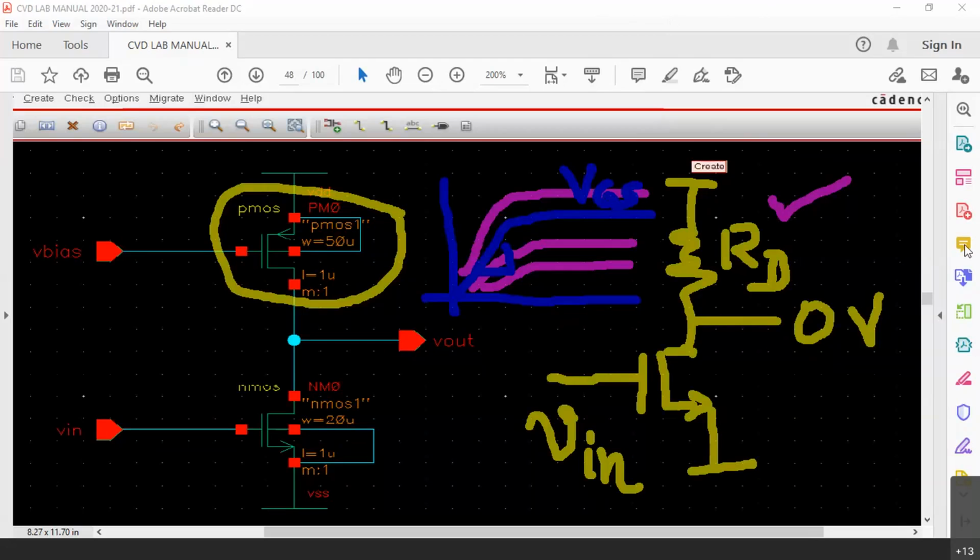Because when we fix the value of the resistance, now PMOS is replaced with the resistor, that's all. That ohmic drop across the transistor also will be there. It is V equals I into R, which is going to be applicable in both the cases. Instead of the physical resistor, we are connecting the PMOS as the resistor. But now PMOS is also working like a resistor only. So that way power consumption will be there. Or ohmic loss will be there across the resistor because there is a drain current flowing. That is not the answer. But you are nearer somewhere.